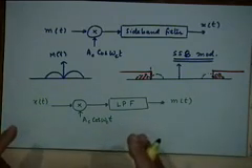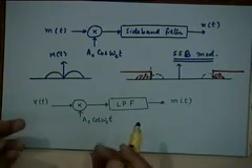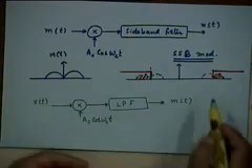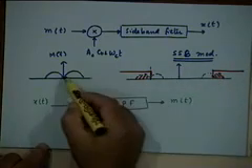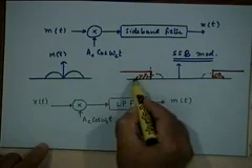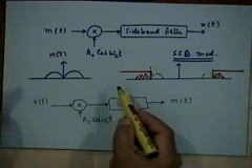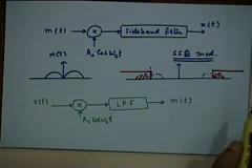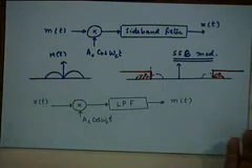Look at it in the frequency domain, it should become obvious. When you are multiplying with Ac cosine omega c t, remember what operation you are doing? You are carrying out a frequency translation by minus fc and plus fc. So let us say you have this component. When you translate it by minus fc, it comes here, and this portion comes here. So you get the baseband spectrum that you wanted, and the plus fc component goes to the neighborhood of 2fc, which will be eliminated by the low pass filter. So there is absolutely no difference in the demodulation process. It remains the same.